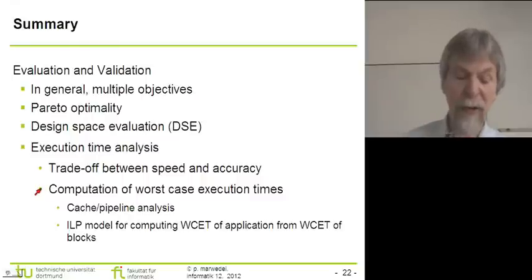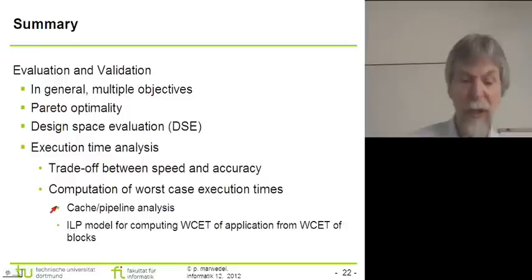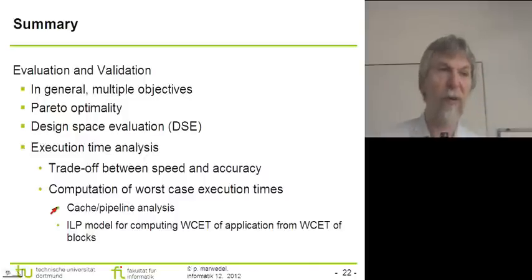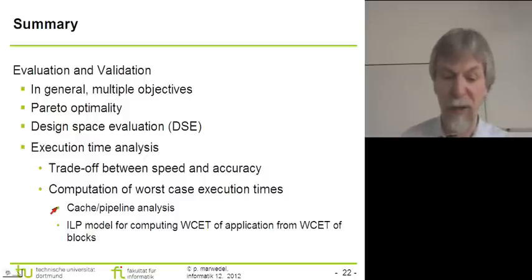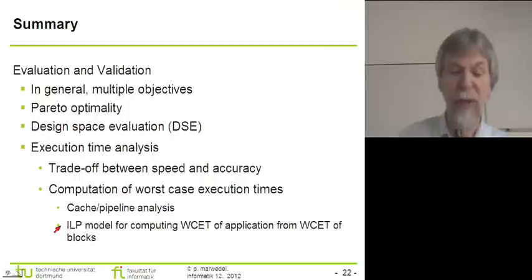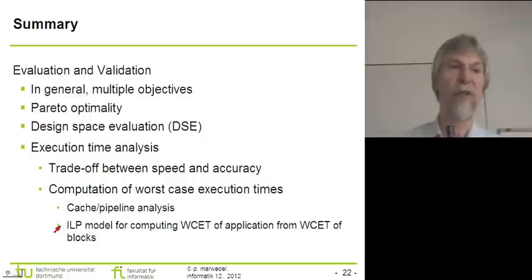And then I looked at the computation of worst case execution times, where I introduced the different steps that we need to look at. I briefly talked about one idea that we are taking into account when we do the cache analysis. And also I presented the IPL model for computing the worst case execution times from the worst case execution times of each of the blocks.